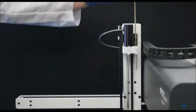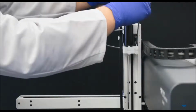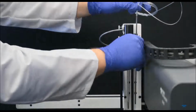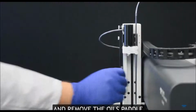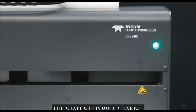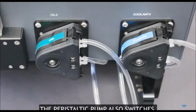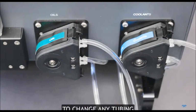To change a sample probe, you can see we have the stainless steel sample probe here that we're taking out. And then we put in a carbon fiber probe that we typically recommend for coolants analysis. You can align the bottom of the probe to the tip of the stir paddle to give you a nice indication of where to set it, and then tighten it down, move your paddle. The LED will automatically update from green to blue, and the peristaltic pumps on the back will automatically switch when the rinse station is moved.